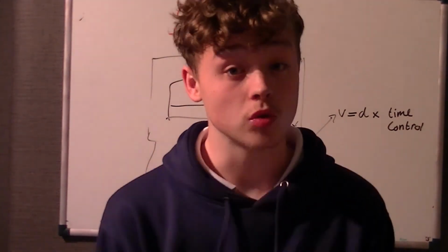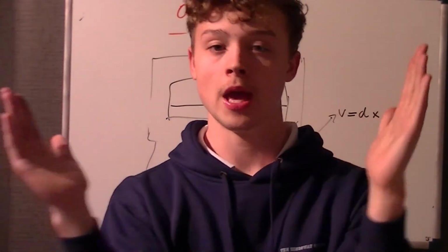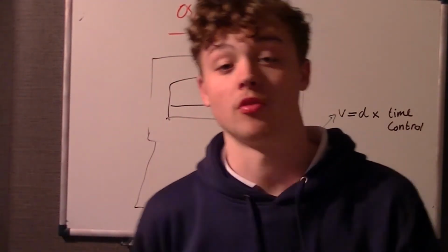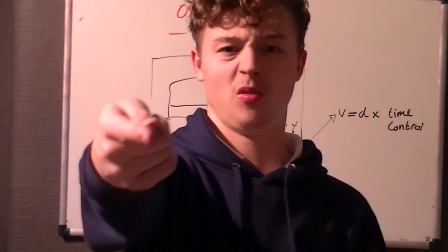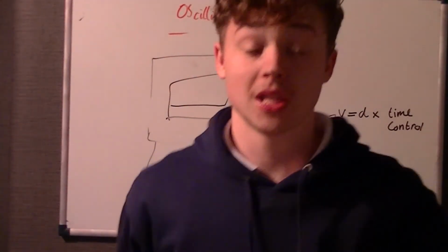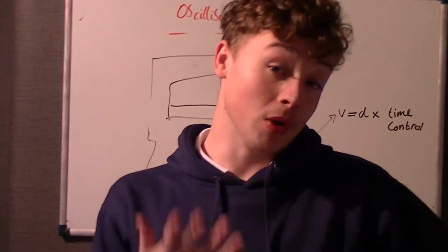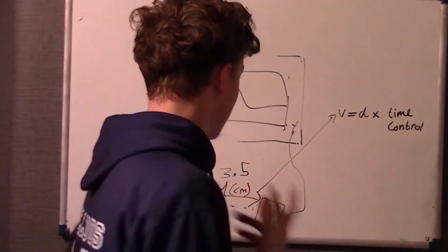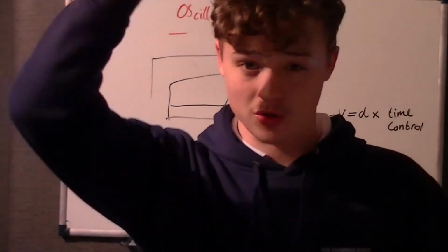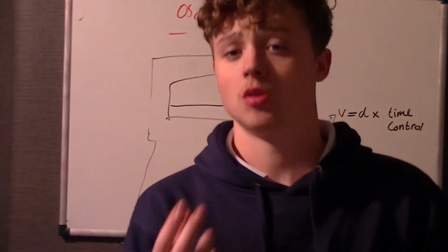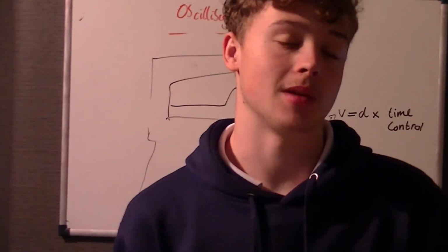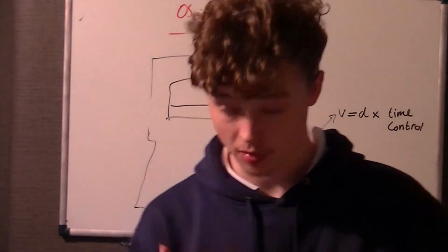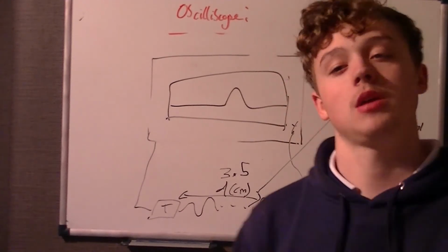If you increase the potential difference across the X plates, the frequency is increased because the bars are a lot closer together on the screen, if you think of it that way. If you increase the potential difference in the Y plates, it's like you increase the Y gain. Well, you don't increase the Y gain, but you increase the peak potential difference.